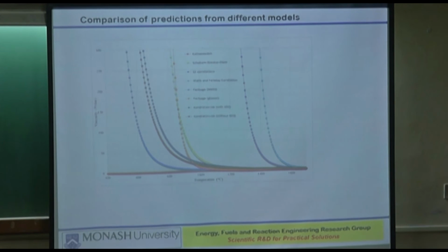If you lower it early, and you don't know what is early enough, then it will be a semi-solid and it will not rotate anymore, and therefore the experiment is gone. So you have lost your molybdenum crucible, that is $200. The rotating spindle and the knob, that is another $400, those are gone.